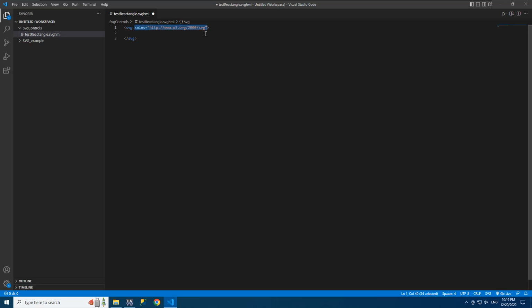But in the case of Siemens and WinCC Unified, we need to declare two namespaces. I will remove this one. Namespaces are written with the prefix xmlns: and the name of the namespace. The first namespace we need to connect is hmi. Let's add it: xmlns:hmi. It needs to be assigned a URL, by which the subsequent program, in our case WinCC Unified, understands how to work with it.